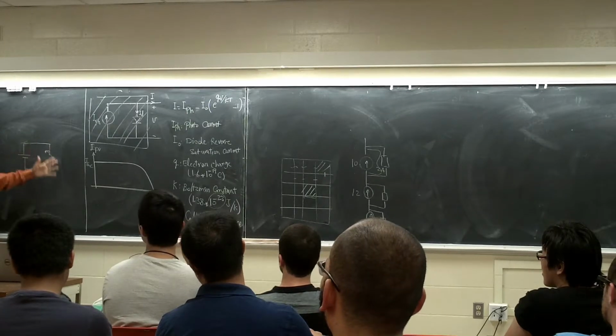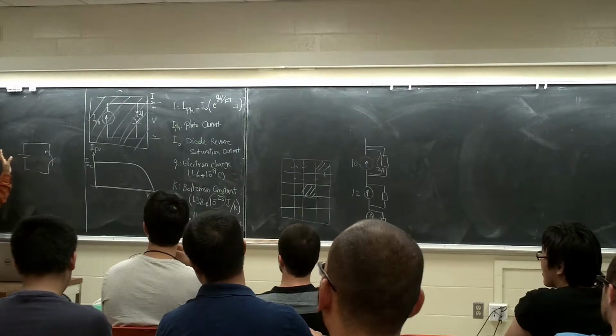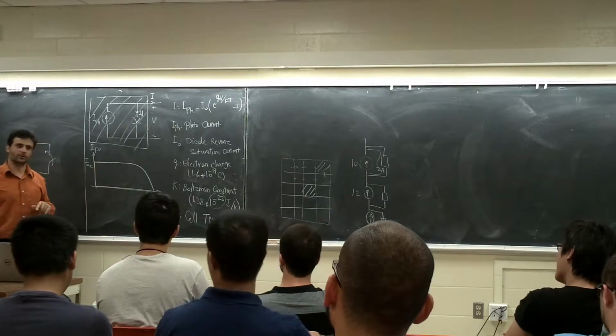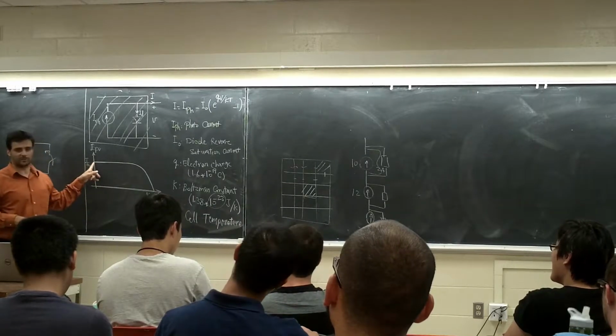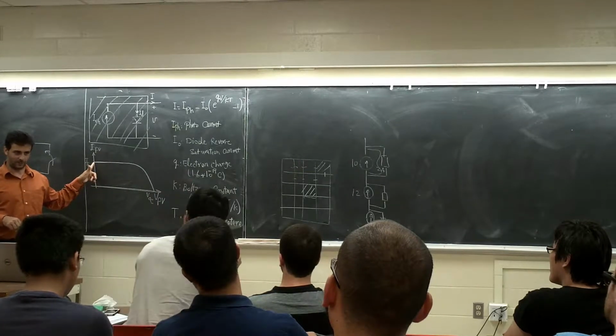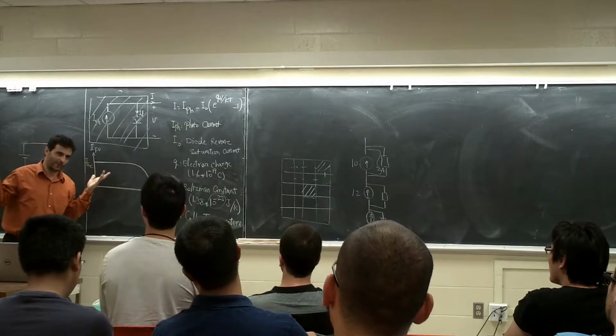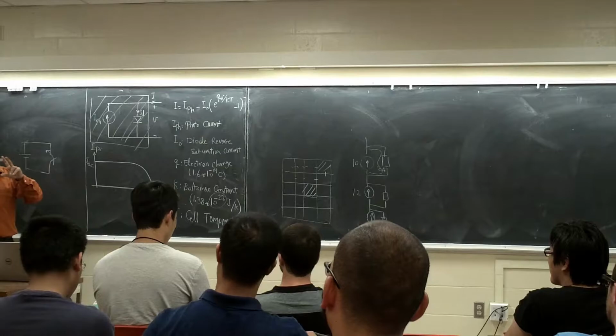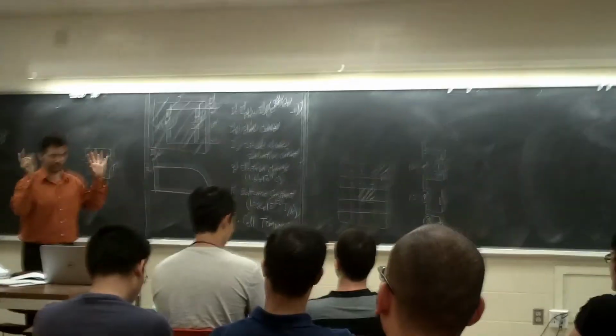It's going to kill the battery, maybe kill yourself also, it's going to burn you. But with the solar panel, don't worry, you can short it. The current is going to max out, maybe 6 amps, 7 amps, 8 amps, something like that. So it's not going to kill anybody, it's not going to be a huge current. That's a good thing, it's kind of protected. It's not like a DC voltage source, when you short it, boom, it's going to go crazy, you know what I'm saying?